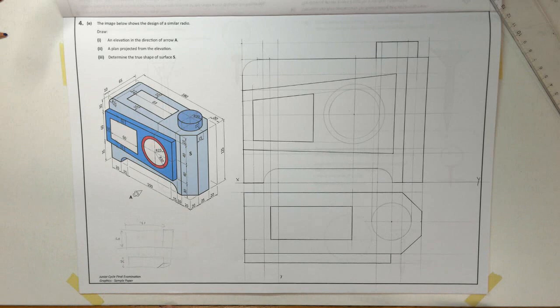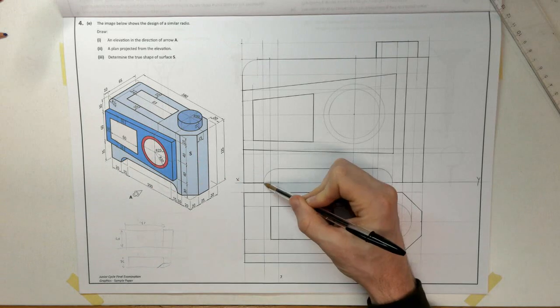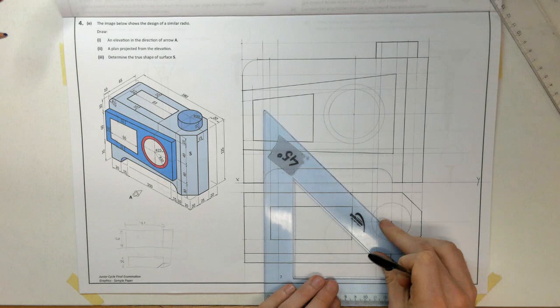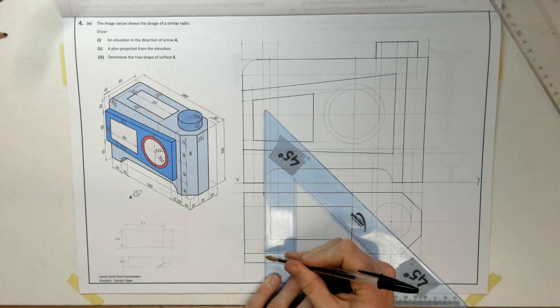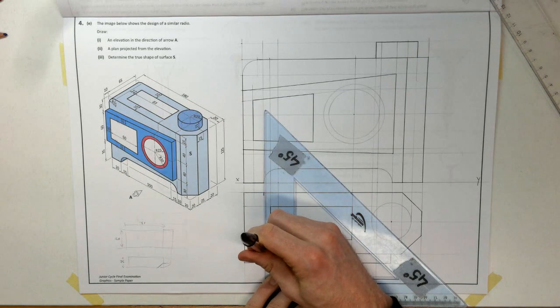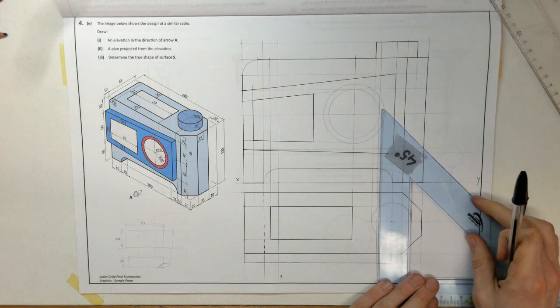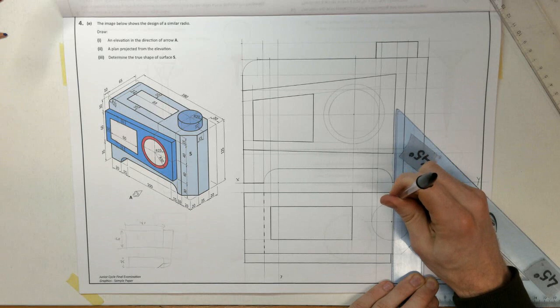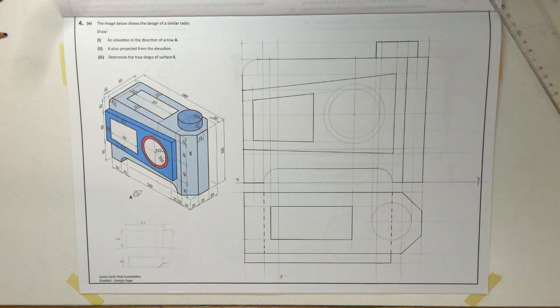So once I've got my elevation plan done, I need to ask myself, is there any hidden detail that is going to be in this drawing? So looking, we've got this edge running underneath, which is represented here, and extend it on. It's going to be the same on this side. So got that coming down, so hidden detail, and it's going to stop short. It's not going to go the whole way through because this little part, that 10 millimeter part, is for here, and there's no cut through that, so it will stop short there. The same on this side, so project it down. Okay, so that's my elevation and plan done.